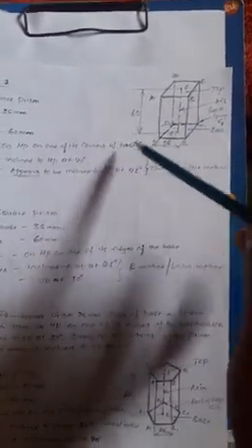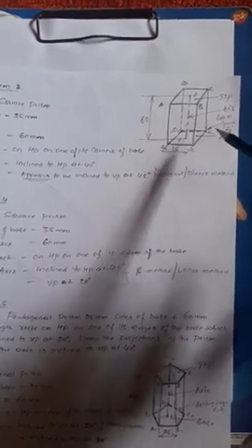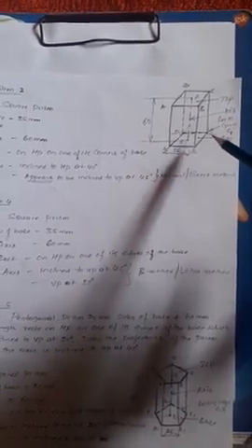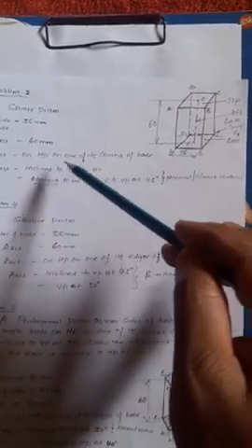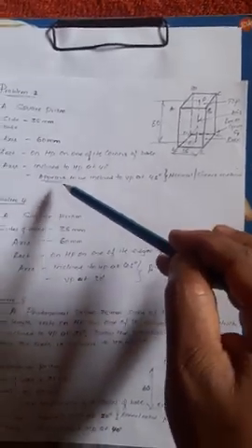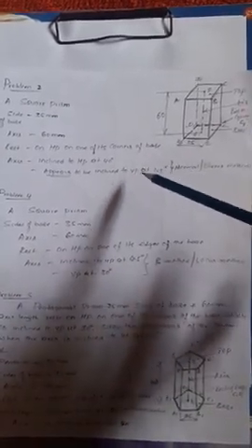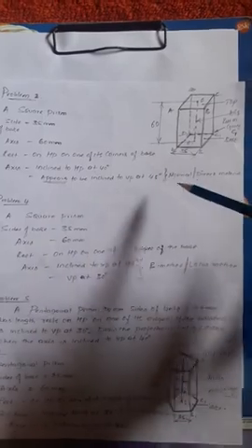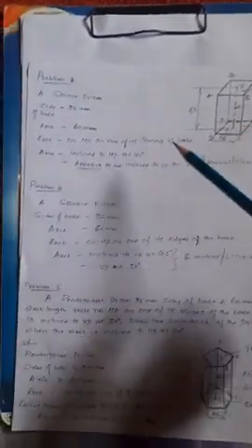Resting on one of its corners, take any one corner, always the corner on the right side of the solid. Then the axis inclined to HP at 45 degrees, that you show in the VP, and the axis appears to be inclined to VP at 45 degrees, that you show in HP. Since the word "appears" is there, it comes under the normal or direct method. Try to solve this problem.